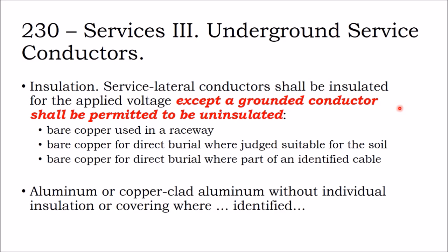So do I need to use solar cable on a project if my cable is otherwise rated for 600 volts and listed for the environmental conditions of a wet, or high temperature location? It may depend on your inspector.